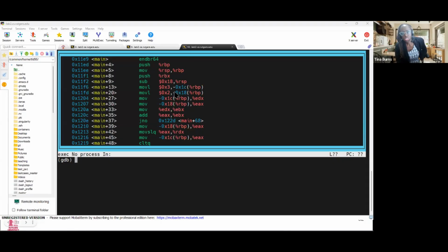This is going to give you your main code, and it also gives you a little bit more detail here. What you'll see is that these numbers, R3 and R2, are telling us that we're moving into these particular memory addresses for the stack there. So this is storing my A, this is storing my B. And then it's going to take this one and put it into this memory address.